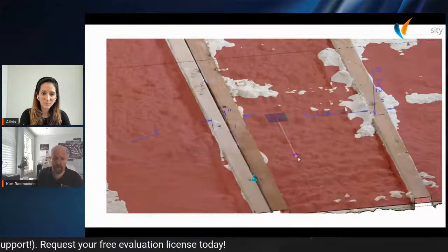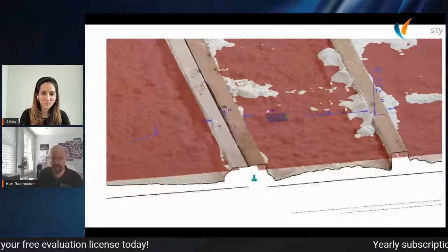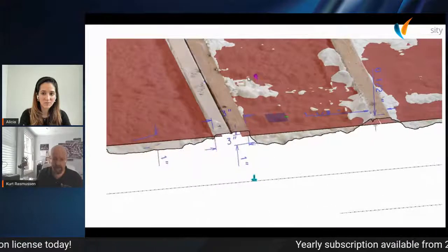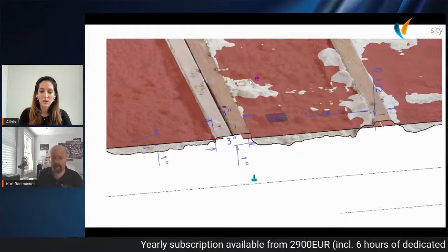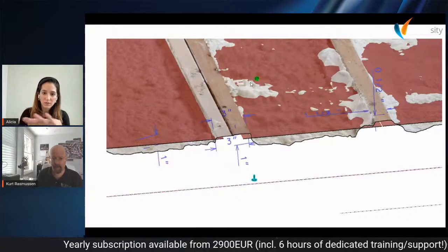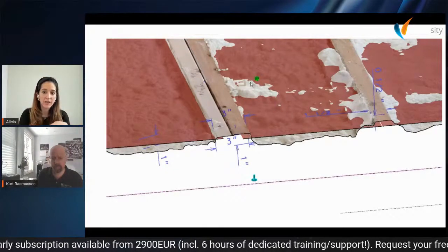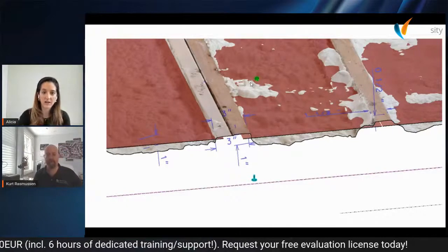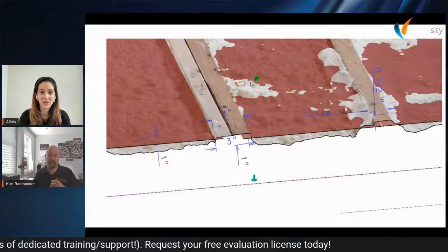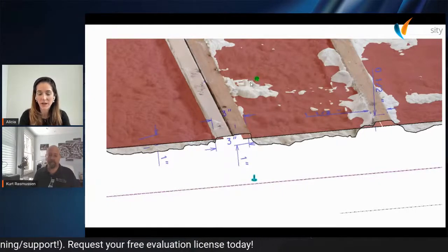I have the measurements of the studs. Those two studs together are 3 inches. And then you see here that I actually showed the depth of how much we were lacking underneath that R21 value. So the red indicates where the insulation should have reached, right? It should have been there. Yeah, okay. And the white is the actual insulation that they put. Yep.